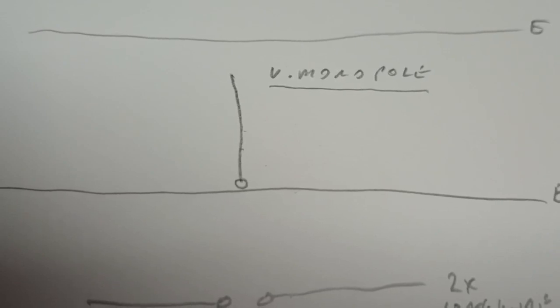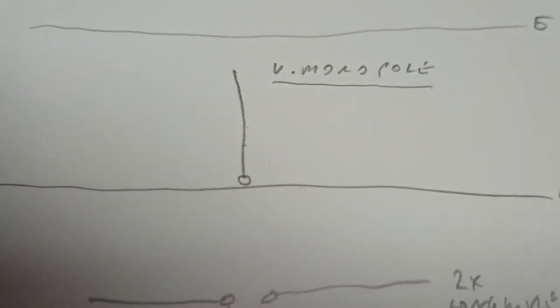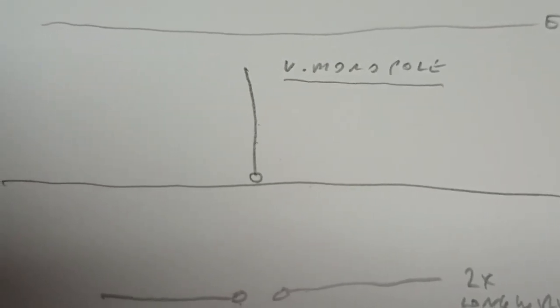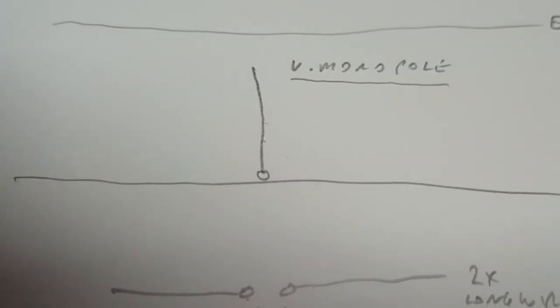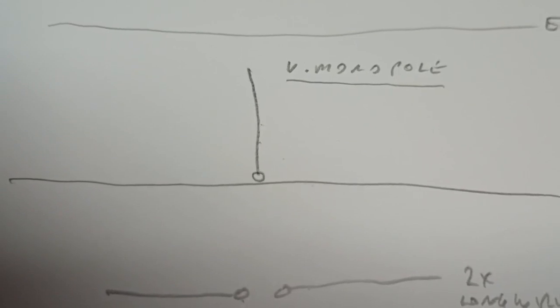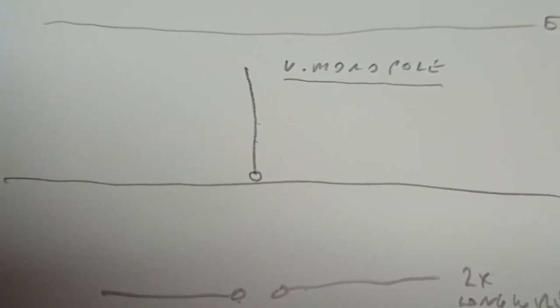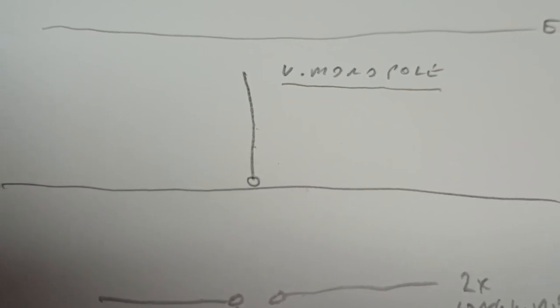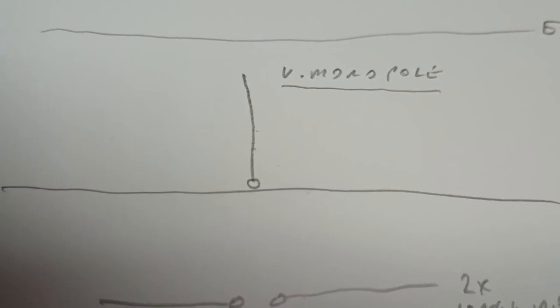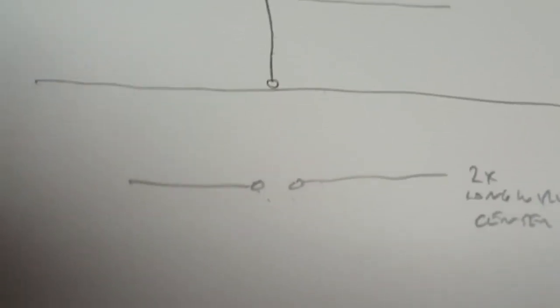That is not for purposes of the antenna. That is for initially coupling the energy from the transmission line into the field space between the bottom of the antenna, think the first quarter inch of that vertical wire, and the ground. Then thereafter, charges on the antenna wire can couple to the ground.